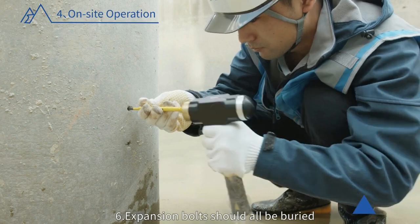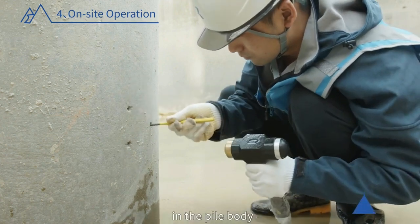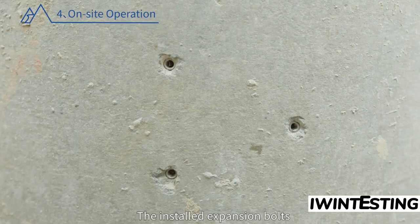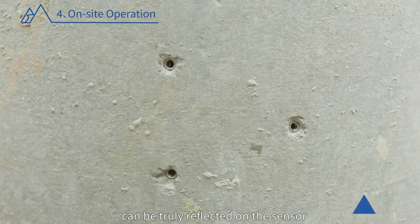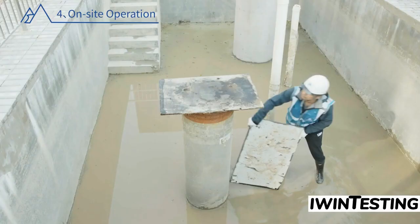6. Expansion bolts should all be buried in the pile body. The installed expansion bolts should be in close contact with the pile body to ensure that the deformation of the pile body can be truly reflected on the sensor.